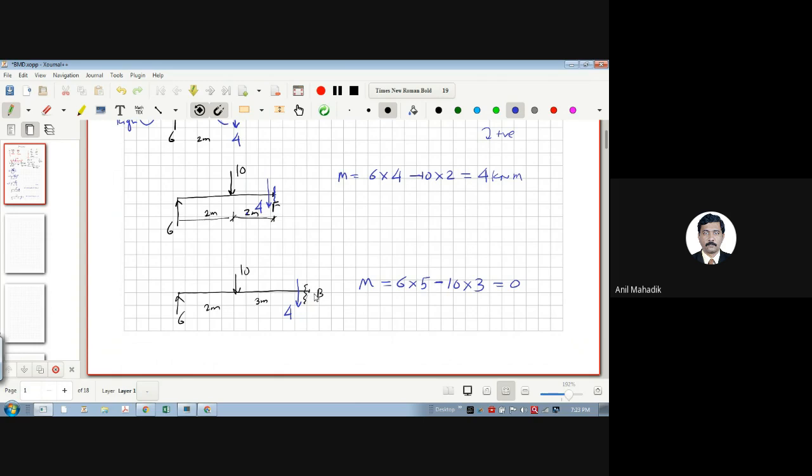So all of you know that at a hinge connection, we have the bending moment at 0. So whenever there is a simple support like a hinge or roller, we have the bending moment 0. So I will not draw any bending moment at this point. So there will be only shear force.